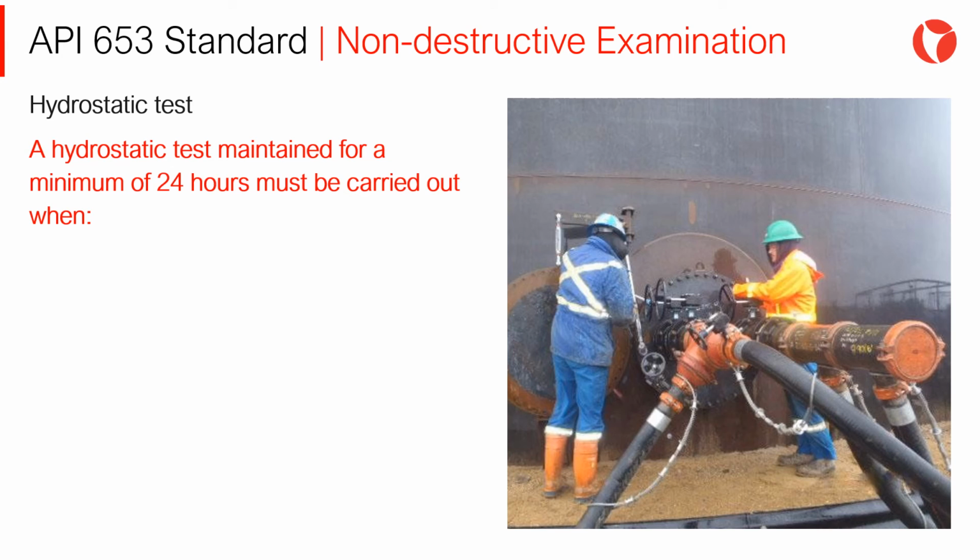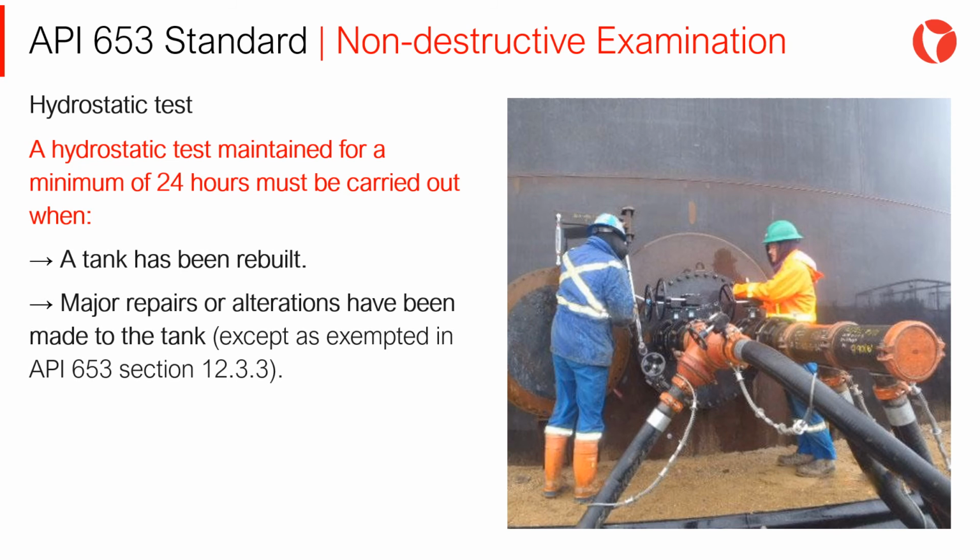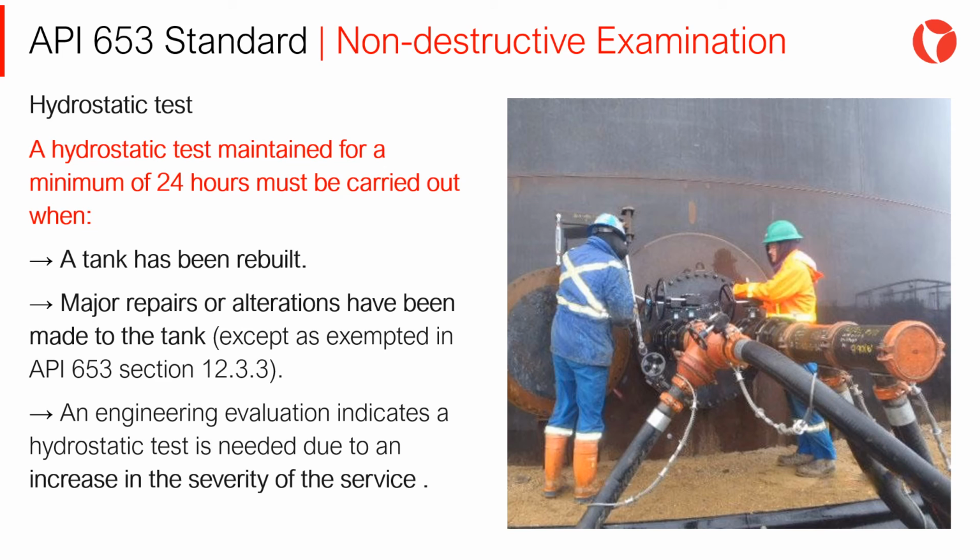Hydrostatic test. A hydrostatic test maintained for a minimum of 24 hours must be carried out when a tank has been rebuilt, major repairs or alterations have been made to the tank, or an engineering evaluation indicates a hydrostatic test is needed due to an increase in the severity of the service.